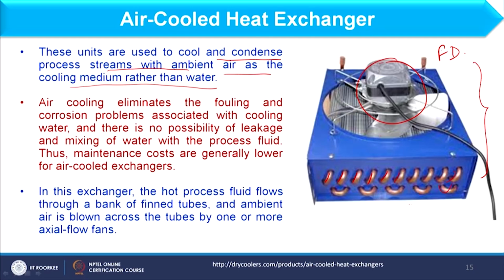On the other hand, we can place the fan at this side instead of the top side. In this case it basically sucks the air, as it is placed after the operation. So this type of fan is called an ID fan or induced draft fan, and this induced draft fan creates negative pressure in the system, and the forced draft fan gives positive pressure in the system.